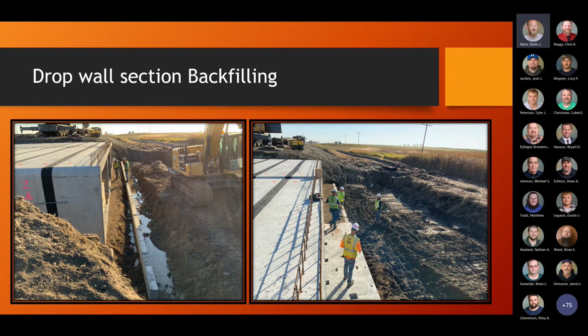I suggested that they use the crane that was with the concrete bucket that they already had on site to place the foundation fill, more accurately with less waste. They looked at me like I was crazy, but decided to give it a shot. They were very thankful for the idea because then they were able to use the excavator right in the hole to place the material on the outside edge while they placed the fill on the inside using the concrete bucket. Using this method, they were able to get the area backfilled more efficiently and timely with less tracking of the excavator.